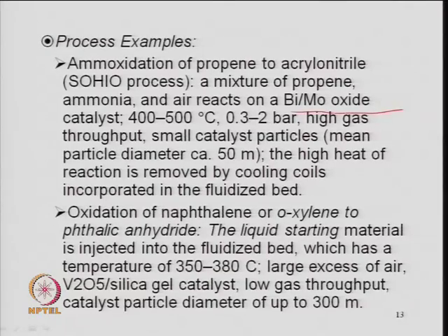Catalyst particles are kept small, right. This is 50 micron particles, right. 1 micron is 10 to the minus 6 meter. So, 50 micron particles, and high heat of reaction is removed by cooling coil. So, the reaction is highly exothermic.